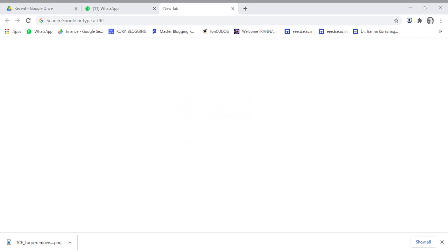So this heat is getting dissipated all around, to all the parts of the circuit breaker. Here we are trying to note down the readings for every half an hour, how much temperature is observed at various parts of the circuit breaker. That is the objective of this test: whether that temperature is within the limit or not.